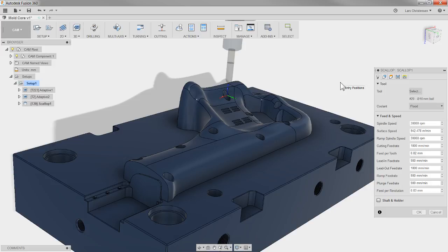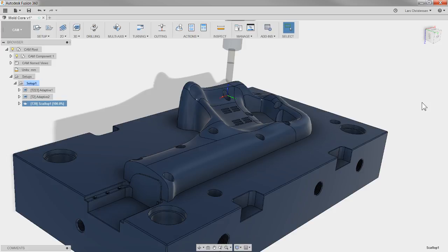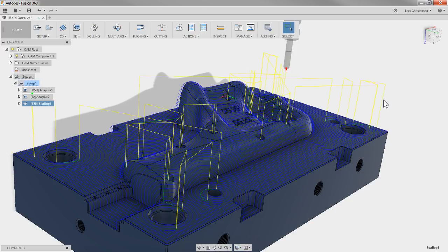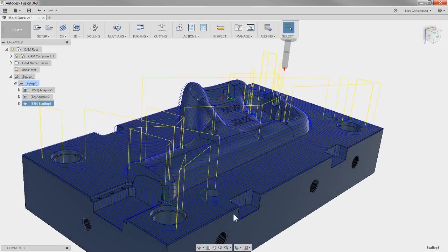Again, whenever I do 3D toolpath, I don't tweak anything. Just hit OK and see what you're getting. And then you can start eliminating from there. Now, again, I'm not going to make this toolpath 100% perfect. It's more about showing you how to eliminate things in the calculation. So, one thing I notice on this toolpath is that it is touching my flat area, but I wanted to get down to that area.